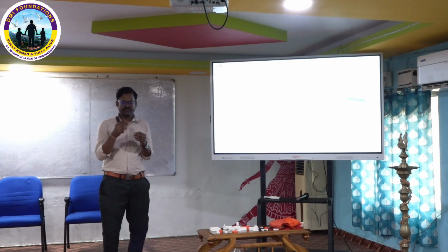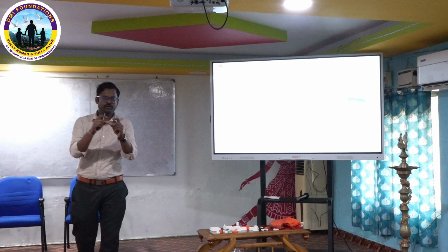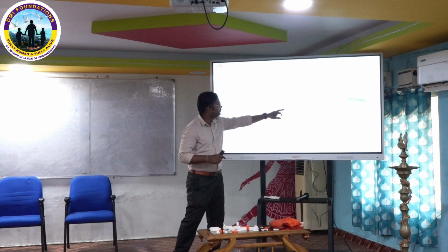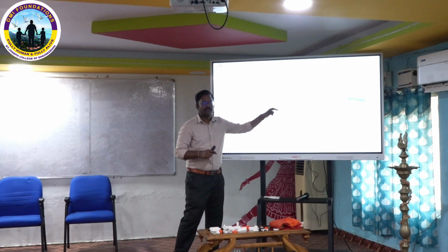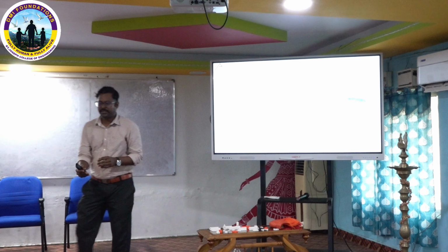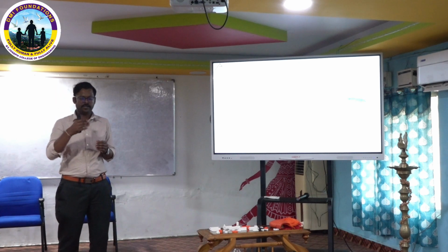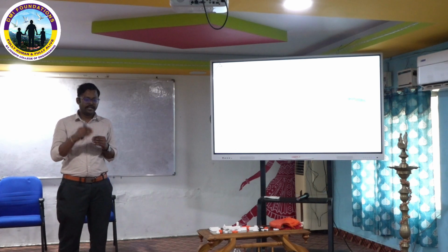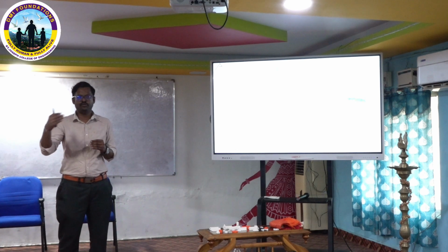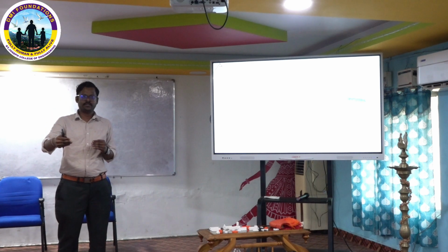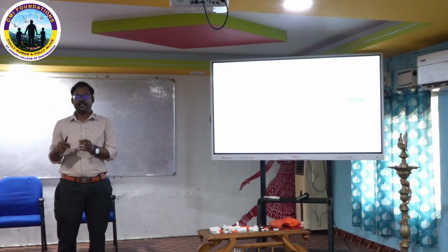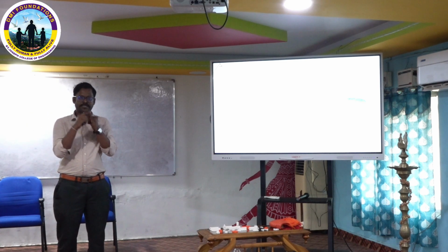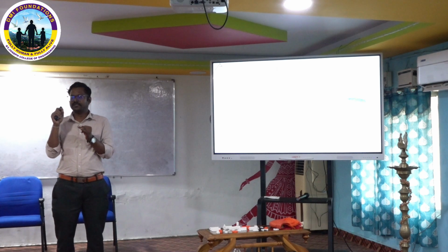What kind of test do we need to do now? I should take one cube, one unit cell, this single unit, and take it into FEA. I give the material property, then I give one mesh type and do the testing. I need to do iterations for different unit cells and different mesh sizes. Then I finalize what mesh size will be good. First, the mesh type; next, the mesh size. What mesh size will be good?